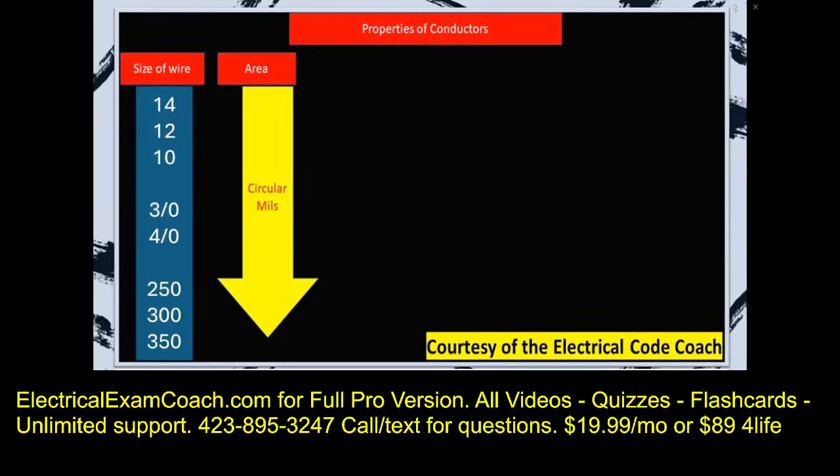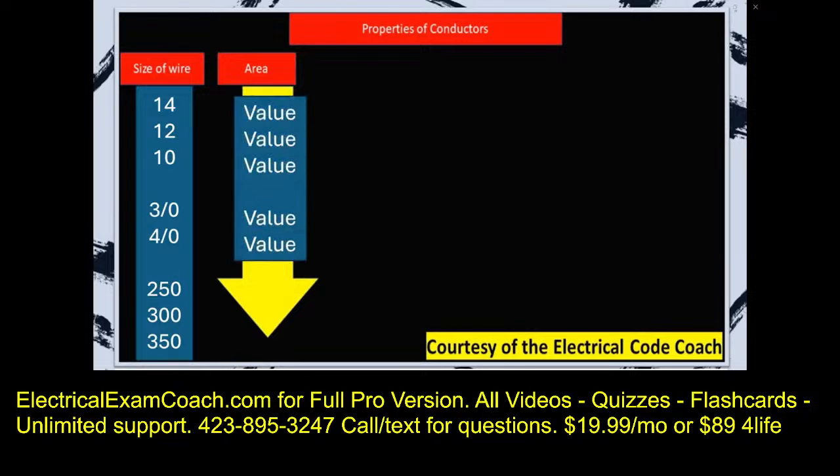14, 12, 10, then it goes down into larger numbers like 3/0 and 4/0, then it goes into the kcmil, and that's where we get those circular mils from. 250, 300, 350. In the next column over, we need to be sure to be in the area section because that's where we're going to get our circular mils value. Each wire has a circular mils value. And you'll notice for the first few wires that there's 2 sets of 12, 2 sets of 14, 2 sets of 10. But if you look over, the circular mils are the exact same size.